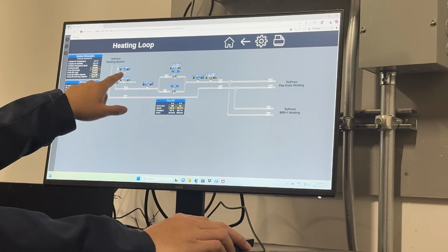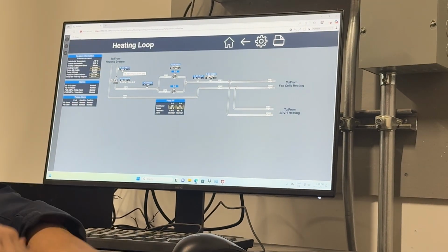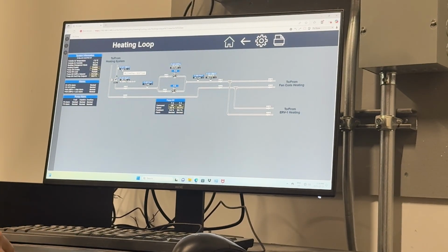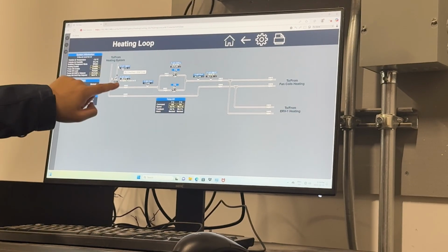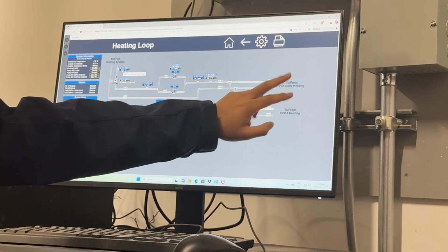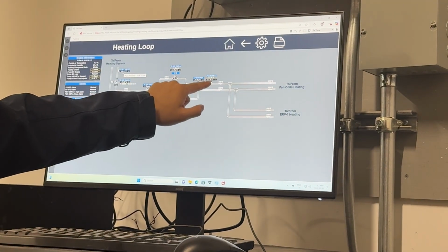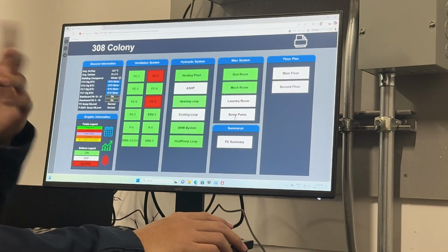Right now, the boiler loop temperature is only 53. If the water-to-water heat pump fails, the boiler supply water temperature set point will increase, right? But increase to 62 degrees C. But we don't want the 62 degrees C to go to the fan coil unit. That's too hot. Then we have this three-way valve. So we always want to maintain this temperature at 52 degrees C. Yeah, that's for the heating side.